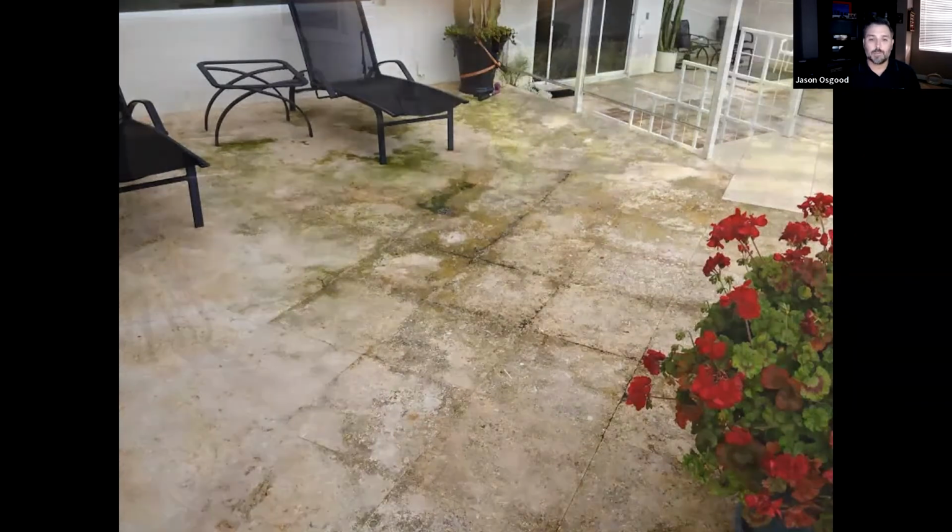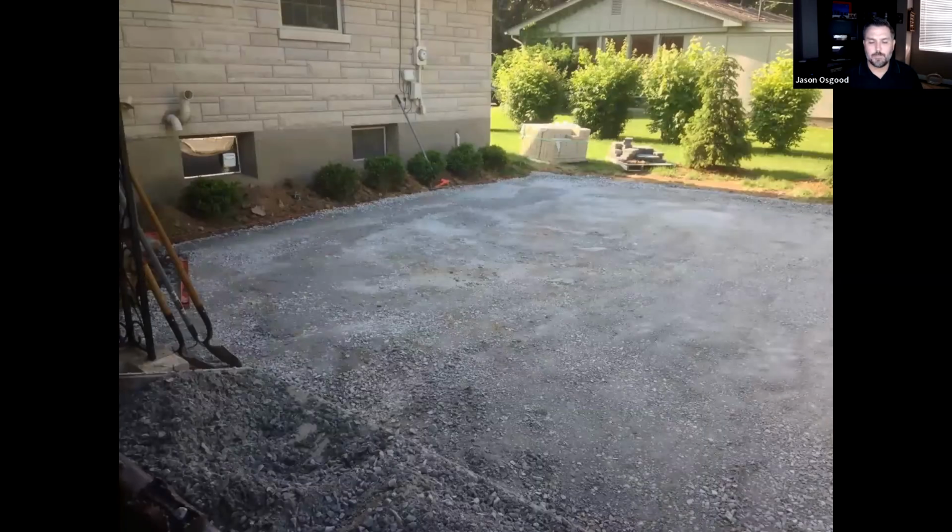Now, when you've done your base properly, this is what it should look like. This deck itself is crowned. As you can see, it rolls off all three sides that you can see, and it's compacted very well. Now, what you're looking at here is a deck that is ready for the bedding material, for the bedding sand. We do not recommend that you lay your pavers directly on the base itself. As you can see in this picture, there are still some large aggregate stones that are sitting on top. You can lay your pavers down, but you will not get a solid locking of those pavers, and the pavers themselves will rock. That's what the bedding sand is for.